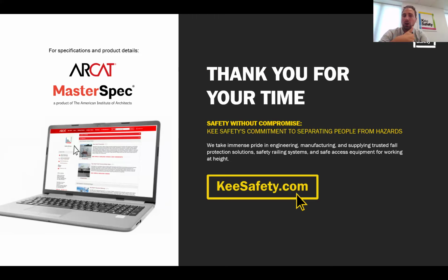There's no engineering involved that you need to test connections. We're not checking tension. We're just looking for basically that it's still fit for use and that it hasn't been vandalized. And it's a simple checklist that comes in our O&M manual. You look at the system, you look at these 7 things, you check it off, and your own employees are able to do that versus having a vendor have to come in and do a formal inspection evaluation of your anchor points or lifelines. So the system makes a difference.